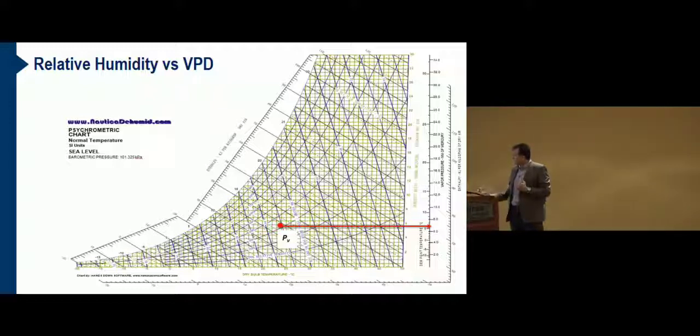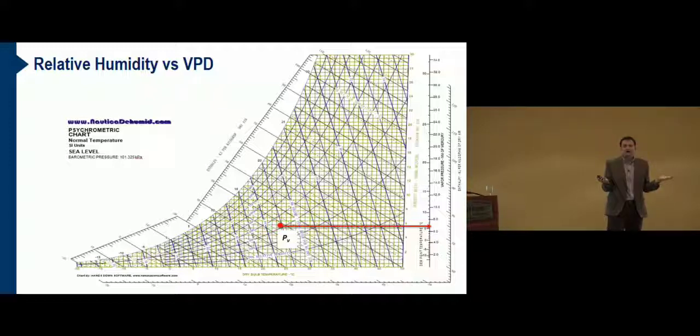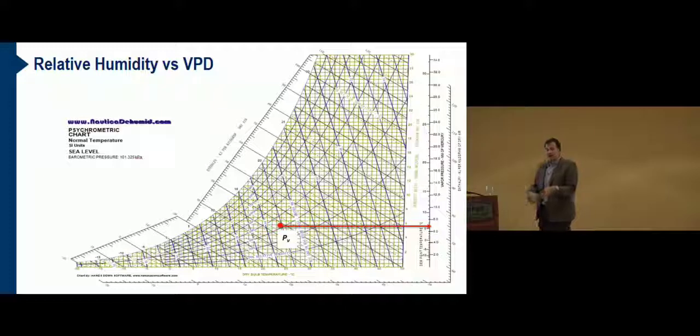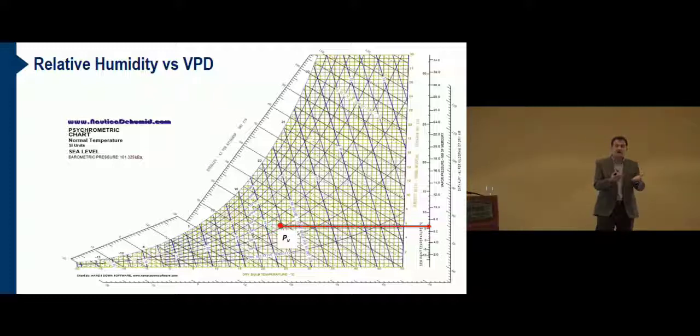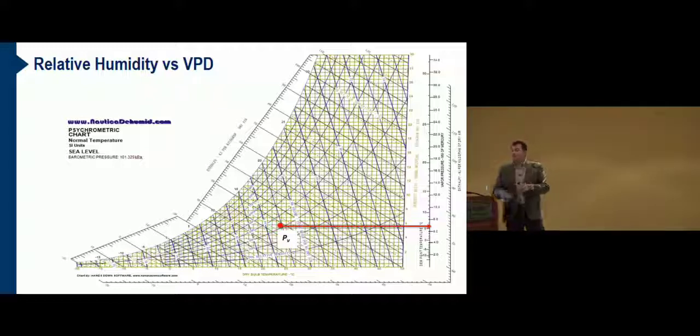So this is a psychrometric chart that Murat showed you yesterday. It's a simple chart presenting the moist air properties, dry bulb, wet bulb, dew point temperature, absolute humidity of air, and the energy of the moist air in one single chart. And this chart can be used, for example, to look at your data. Several speakers again talked about yesterday your climate, your environment, and what type of cooling systems you need to consider.